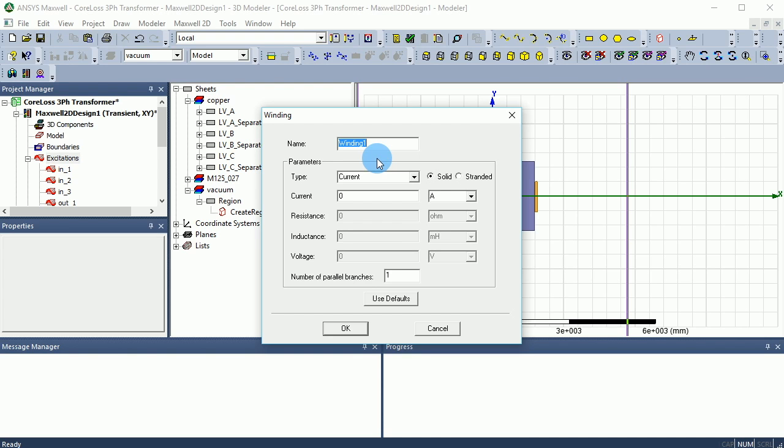So you basically define windings and then you assign the terminals to the windings, and you say this terminal will have this voltage connected to that. So again, let's go with that and say, okay, winding A, it's going to be a voltage again, and I'm going to make sure that the resistance here is 1 milli, the same as we picked the other time.